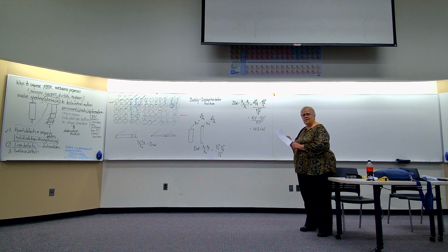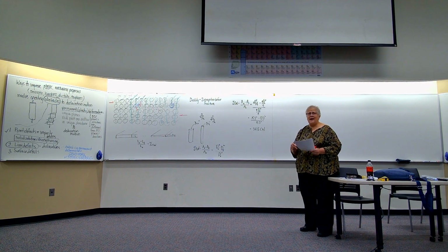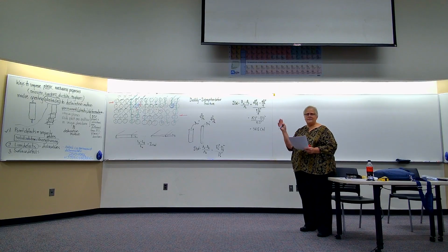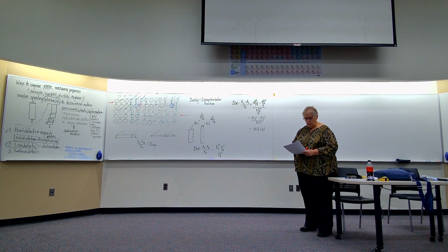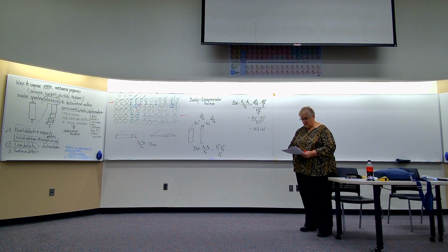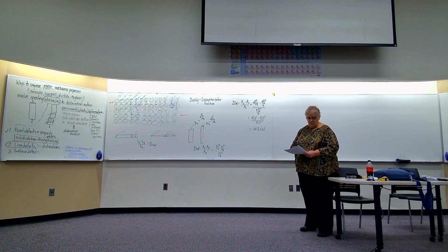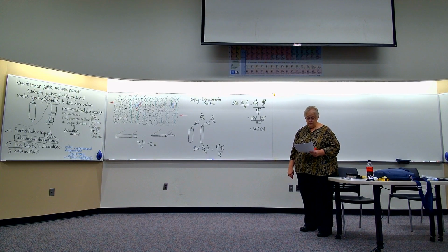Now, this was copper. I can look at this graph. Note that megapascal is on the right y-axis, not the left y-axis. So this is copper. If I have 36% cold work, that looks like it's maybe 44 or so. Granted, this is just an estimate. No, I'm sorry, I was reading PSI. I want to read at megapascals. So at 36, about here, it looks like it's right about 300 megapascal.